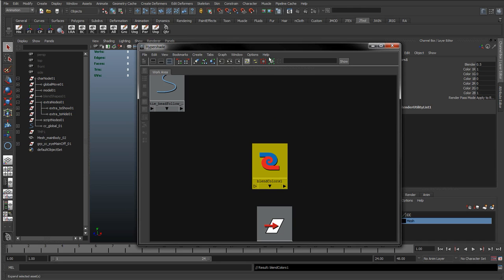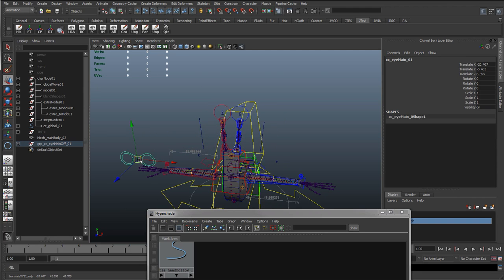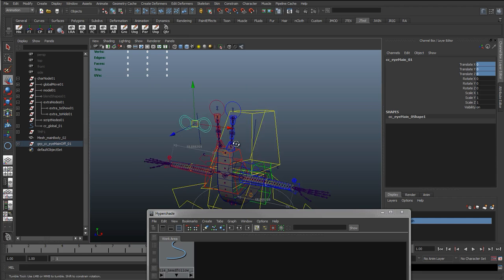have the blend ability, because for a lot of the things the animator would like to preserve the pose, so the arm could be grabbing hold of something, you want to switch it to FK but preserve that pose. So we did that mel script so you can just click between IK and FK and it preserves that pose. But for the eyes, I quite like to have it where if he's focusing on an object, and then instead of clicking a button to switch straight to following it, I like to have that blend, because your eyes naturally will blend from the object rotating up to follow something else.